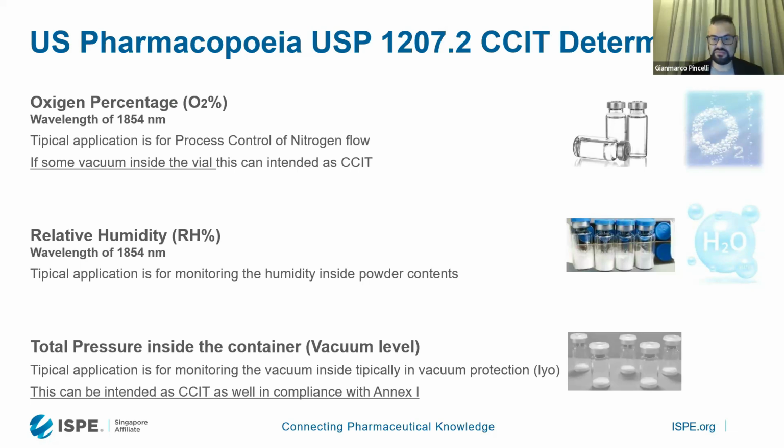If you have 100 millibar, 200 millibars, it means that something was entering the product, but you don't know if it was a real leakage or, we can say, a capping defect on the machine. You are not able to do that. You are not measuring the leakage of the product like on pressure decay and vacuum decay. You are measuring just the effect of a potential leakage on the product.